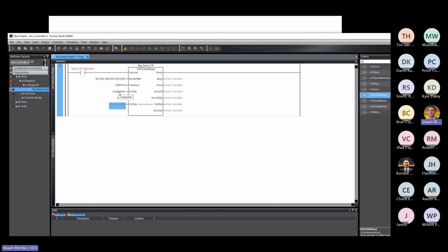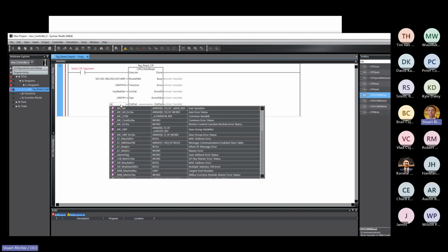Because we know this is a real, we need to bring it into a real, and our PLC will verify that these two data types match. Now, they can be structures, they can be arrays, they can be a number of things. Word of caution, Booleans generally have issues, but every other data type is okay in most cases. But I'll make a tag here. I'll call this myRealVar.